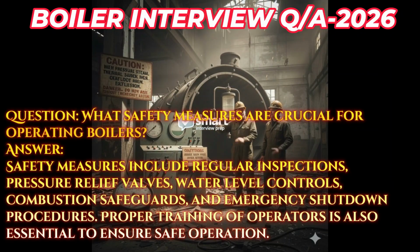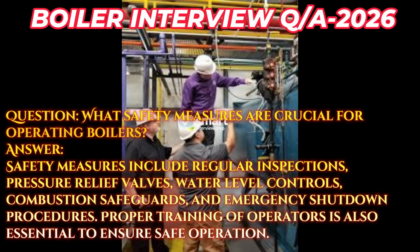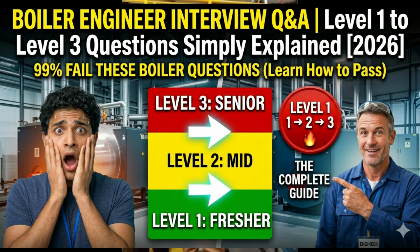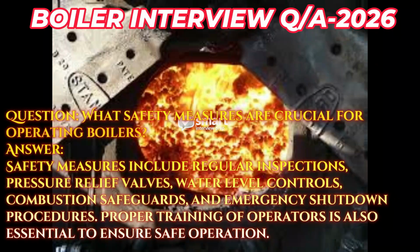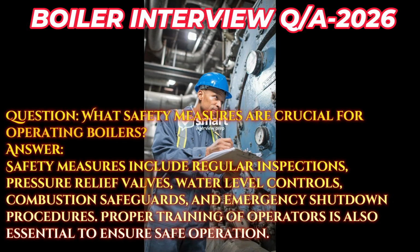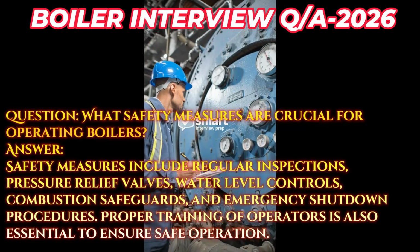Question. What safety measures are crucial for operating boilers? Answer. Safety measures include regular inspections, pressure relief valves, water level controls, combustion safeguards, and emergency shutdown procedures. Proper training of operators is also essential to ensure safe operation.